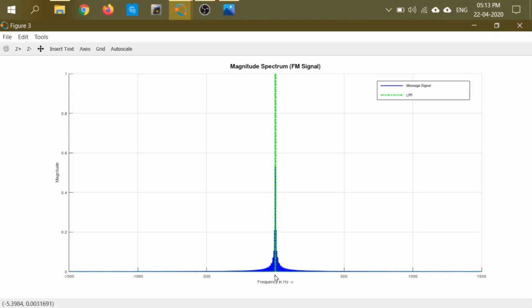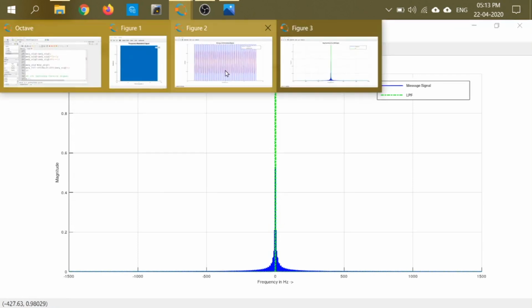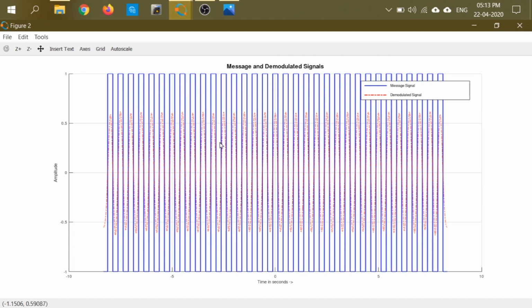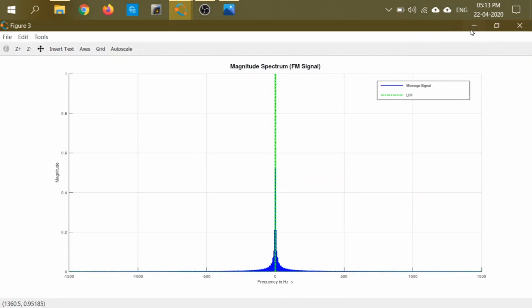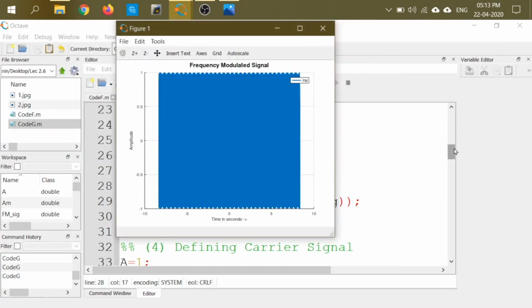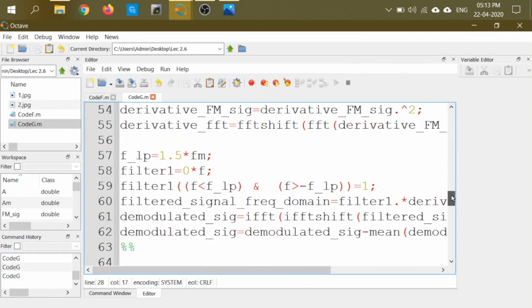So there has been an abrupt truncation of this Fourier transformation terms. So we need to broaden this filter to make that sine signal that we are having in this output, in red output, look like a square wave. So let me just change the low pass filter's cutoff in these lines. Instead of taking it as 1.5, let me take it as, say, 10 again.